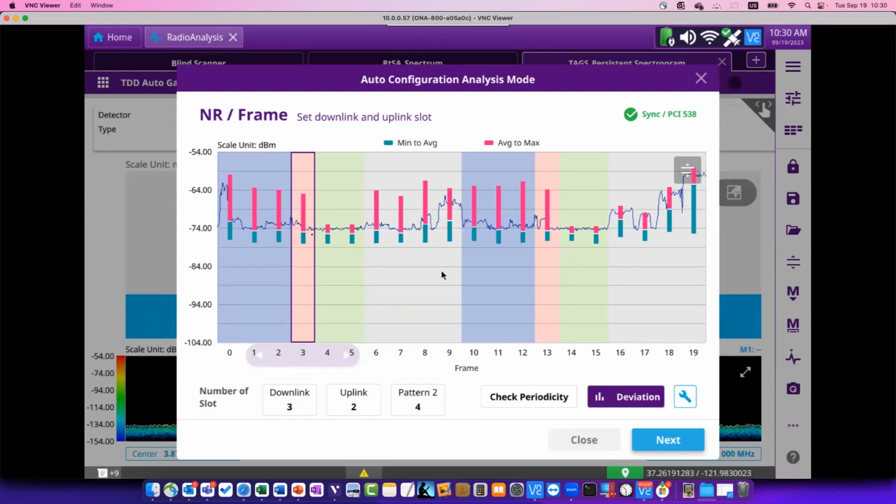These deviations help because the 5G TDD signal is bursty. We don't always have a controlled signal being transmitted. The only thing with some periodicity is the SSB, which happens at the beginning of the frame.